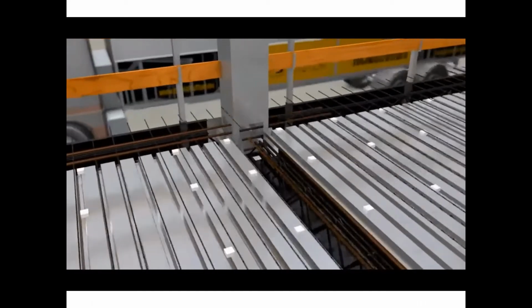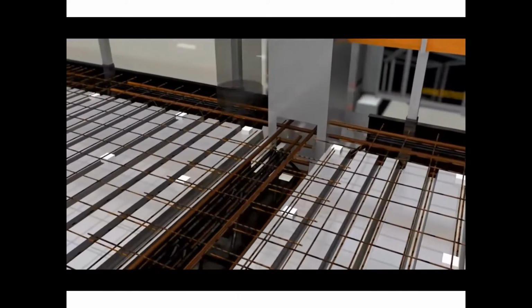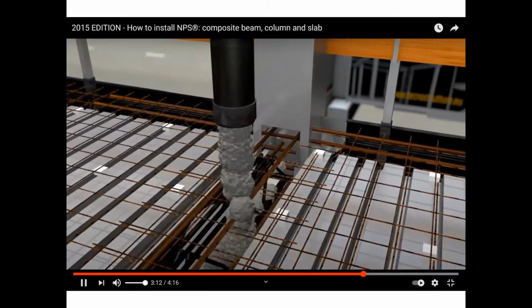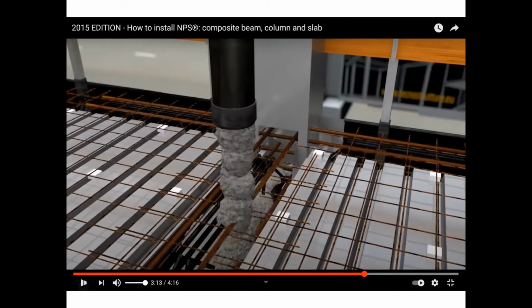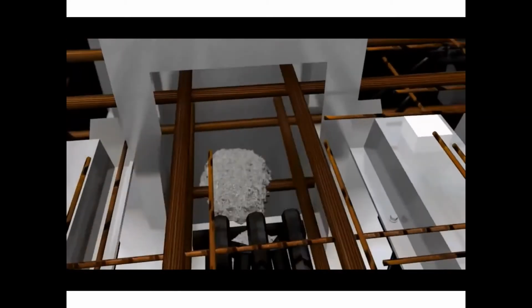We have, I will not say it's a reinforcement, but at least it's reinforcement mesh for shrinkage. Then we will pour concrete. So can you see? We have a steel beam, we have corrugated steel sheet, and we have concrete. All of them will be one unit. So we have composite structure. And the concrete is filling the columns.